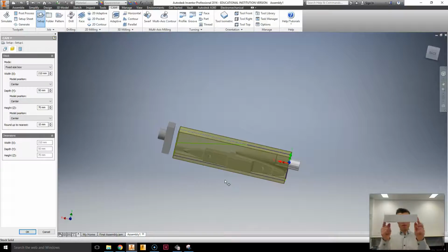Our actual stock here is 223, but we don't want it to be the full length, because the fixture on the end that doesn't have the canister hole grips like a crab claw on either side. And that takes up a bit of space, about 13 millimeters. So we don't want our fixture to be hit. So we decided to limit the size of our stock to 210.